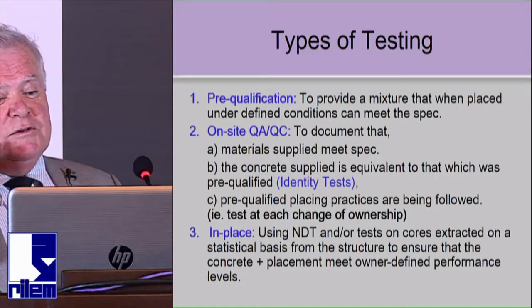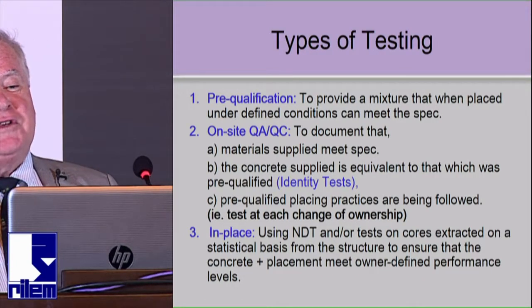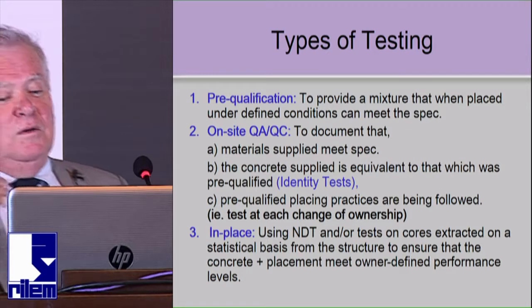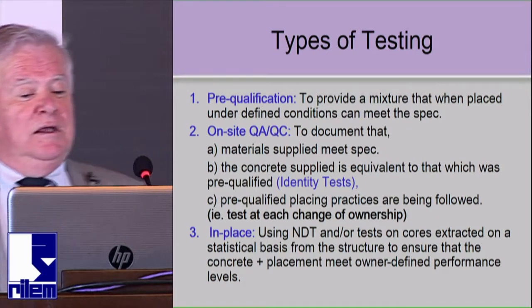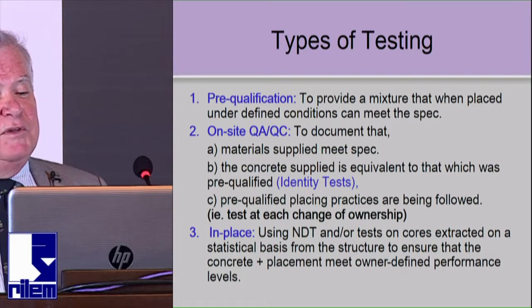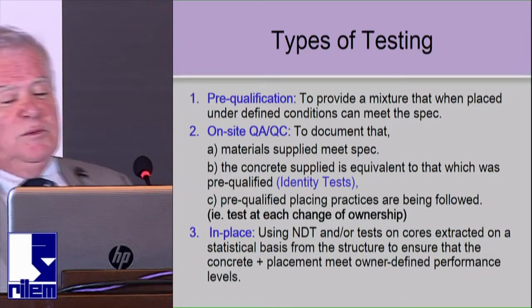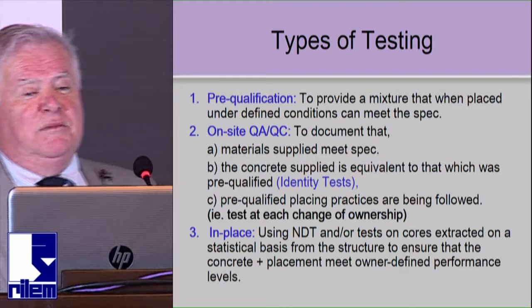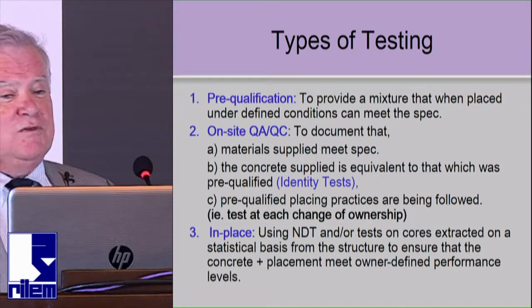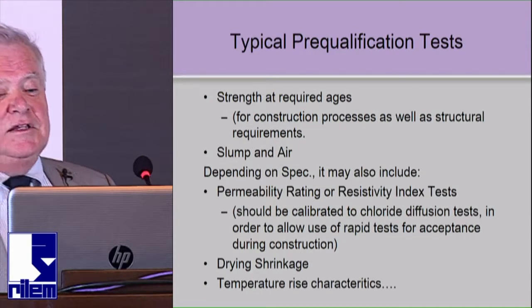Okay. So we want to do pre-qualification testing to make sure that the mixture that's proposed will meet the specification. You want to do some on-site quality assurance to make sure that the concrete supplied is the same as pre-qualified, as I mentioned, identity testing, and you may want in-place testing, which could be non-destructive or destructive tests, depending on that.